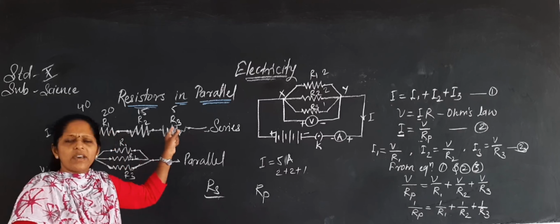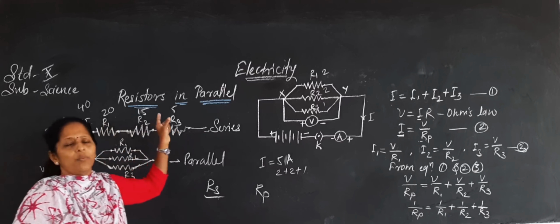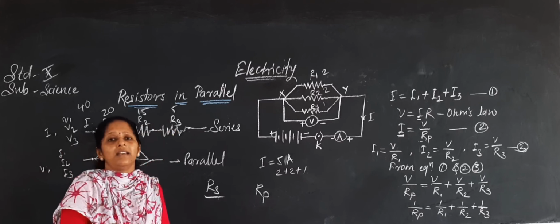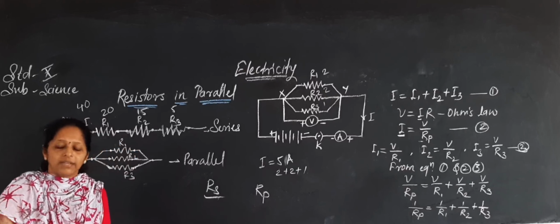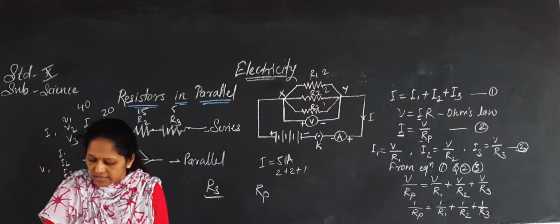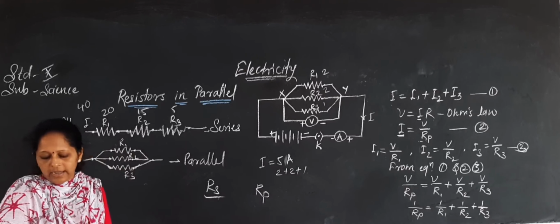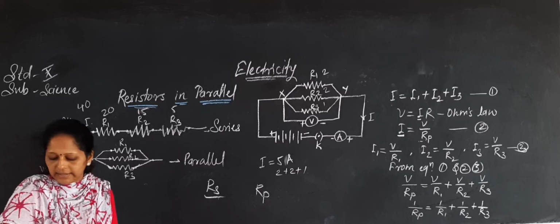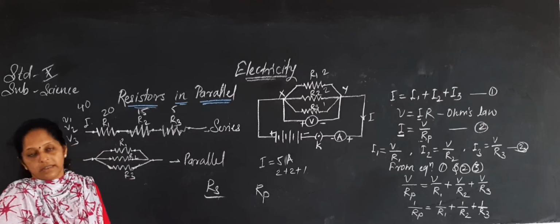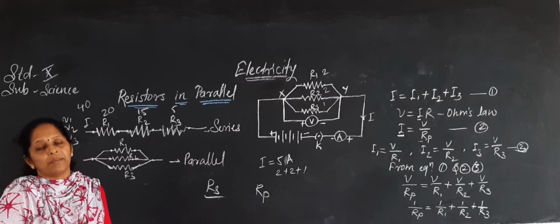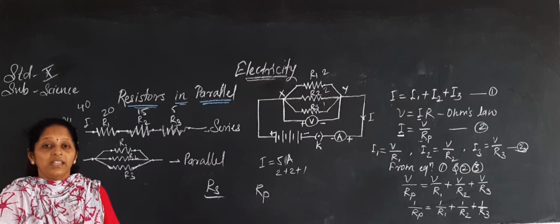So current is constant throughout the electric circuit. However many devices you are joining in our home, the same current is flowing through all of them. Thus it is obviously impracticable to connect an electric bulb and an electric heater in series. It is not a good idea, as we are joining a heater and a bulb.